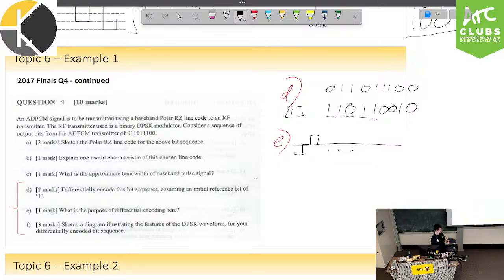Sorry, give me just a second. You're relying on changes in phase, okay? You have pretty much a change in phase between these two, if you were to look at it in any other way, which usually we don't like to constantly change it. We are changing it relative to whatever value we see there. However, in differential encoding, if it stays the same, then we just say, okay, nothing changes. We don't need to transmit something, right? Does that kind of match with what you were saying?